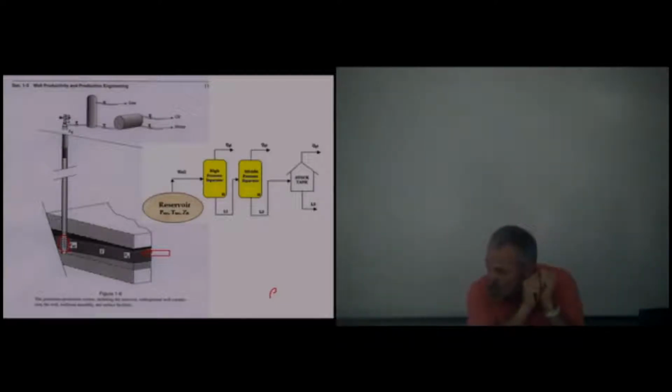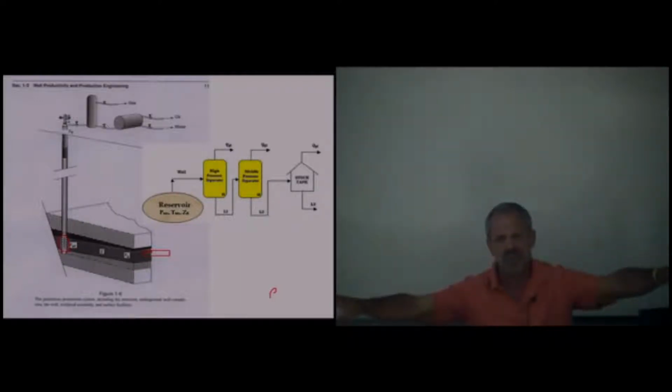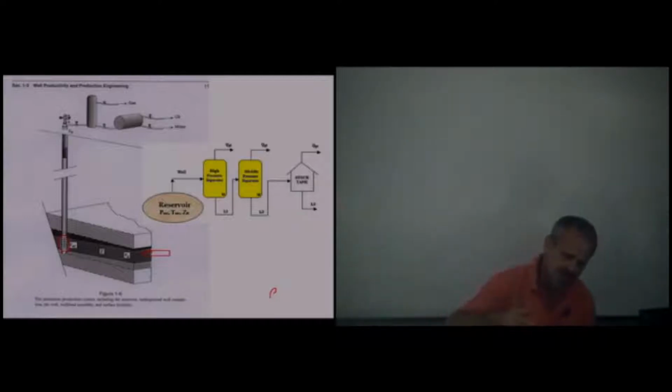And if it's more than the pressure in the formation, we have invasion, or we lose circulation. This isn't as big a problem as a blowout, but oftentimes we damage the formation so much because we lost so much fluid that we lose our reservoir. And also, we're losing fluid that costs us money. So we try to drill our wells balanced.